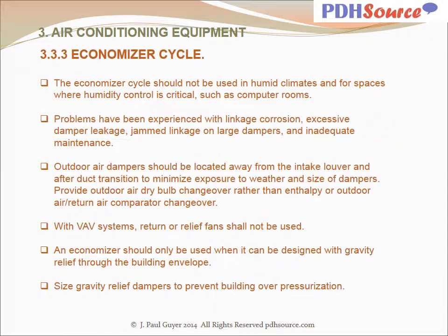An important consideration in air systems is the economizer cycle. The economizer cycle should not be used in humid climates and for spaces where humidity control is critical, such as computer rooms. Problems have been experienced with linkage corrosion, excessive damper linkage, jammed linkage on large dampers, and inadequate maintenance.